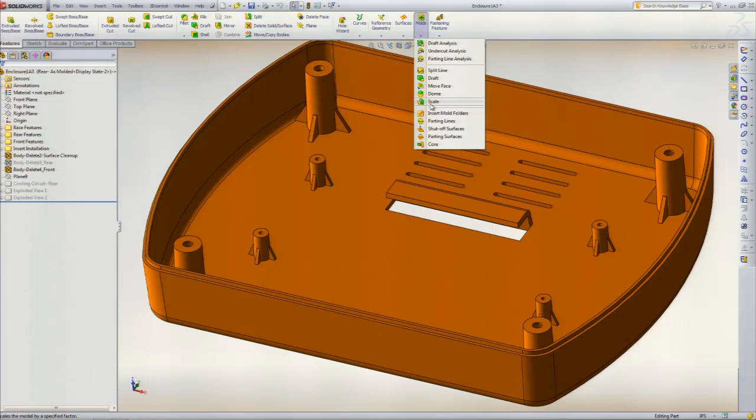What I have to do is, you've heard of shrink in your injection molded parts. We have to incorporate the shrink into your tool. So if the material you select will shrink 0.003 of an inch per inch, for example, you have to increase the overall size of your mold cavity by that factor.